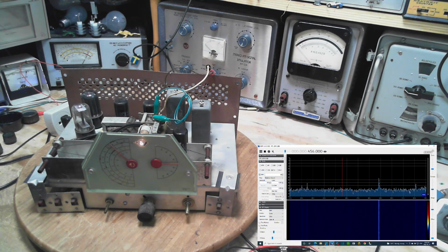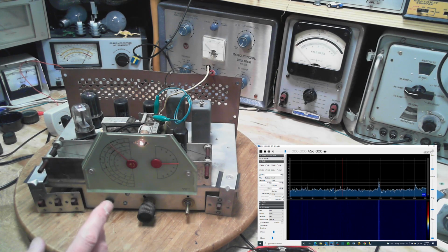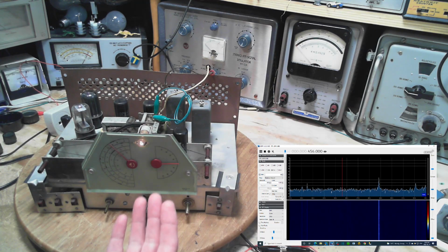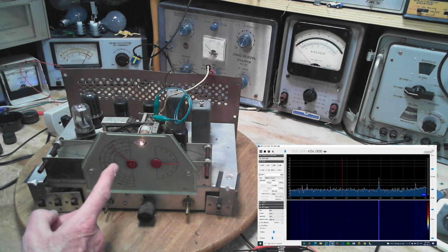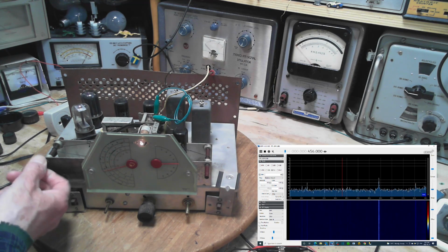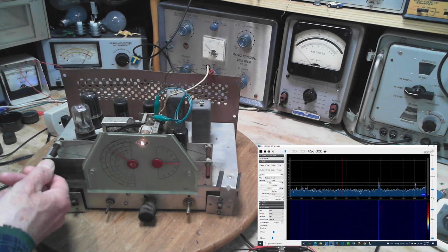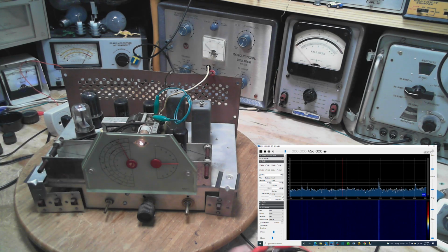Okay, so the question would be now, this noise I'm hearing, is this noise coming from the tuned frequency, or is it coming from the IF straight through? How can it be the tuned frequency? Nothing is being converted. So the radio is only picking up 455, which means tuning this should have zero effect on the radio. And is it true? Okay, well, it's having some effect, but not the normal. Okay, we'll leave it at the quiet end for now.